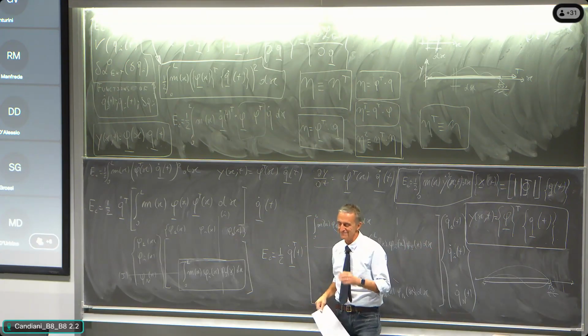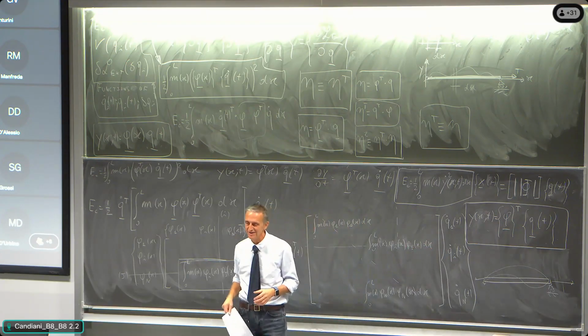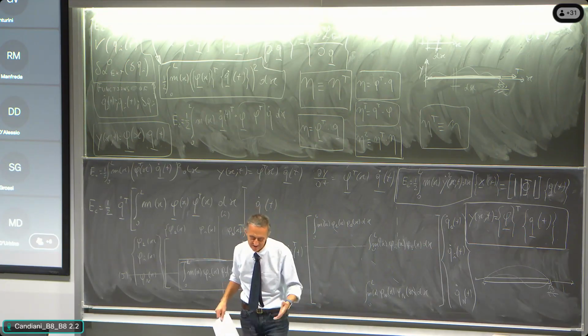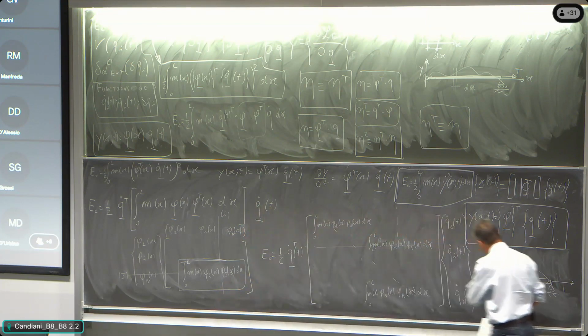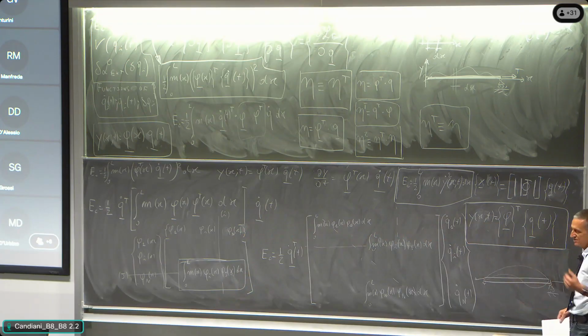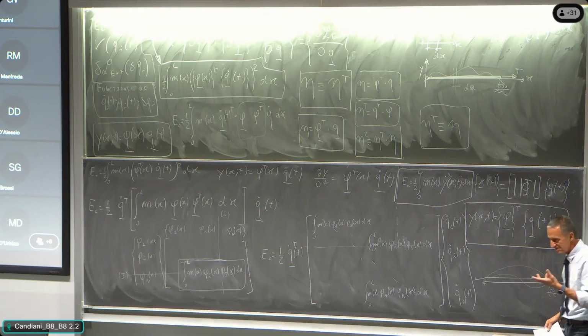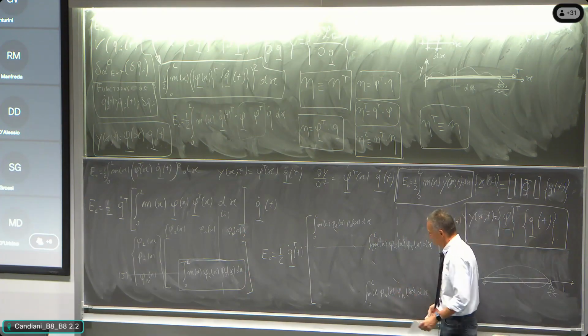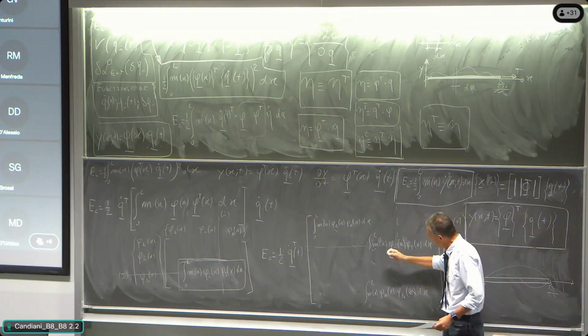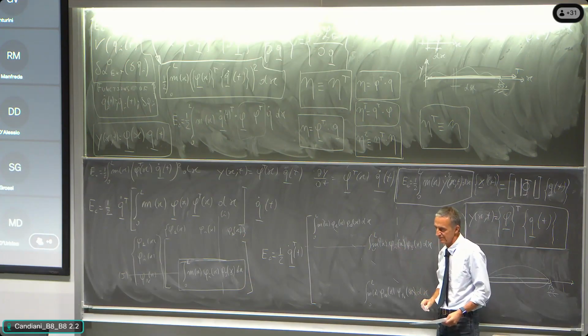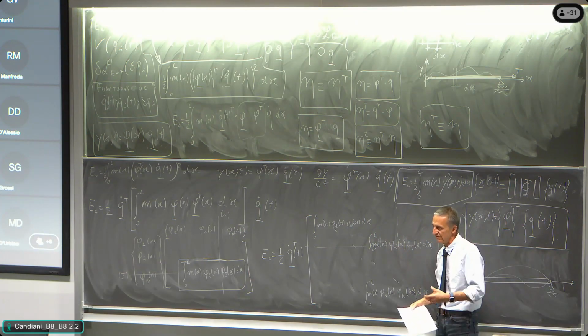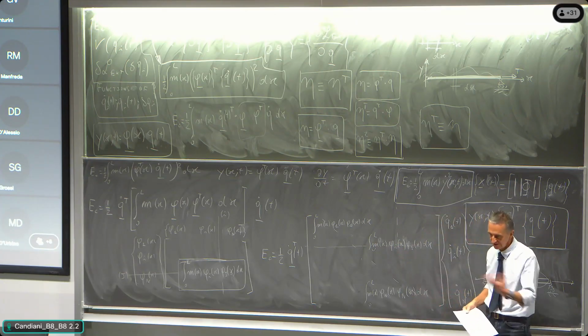So we pretend in this course that you have the concept that what is orthogonal is not the geometry. Of course, in the example we use a constant mass per unit length, so what is orthogonal is the geometry, and it is very clear that this shape is orthogonal to the other one, all right? But we must have the concept that in the general case, it is not a geometrical property. It is a property involving the mass distribution and the stiffness distribution.